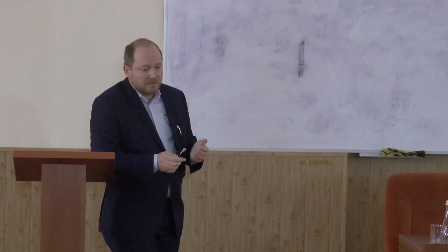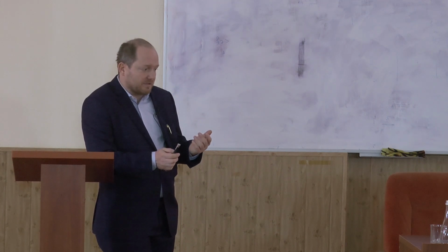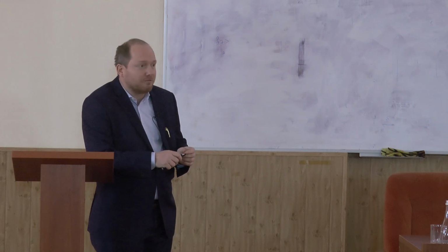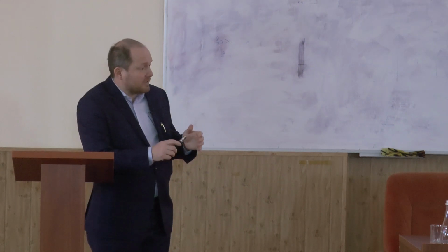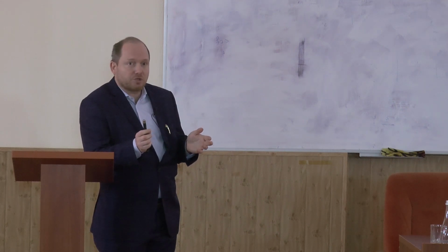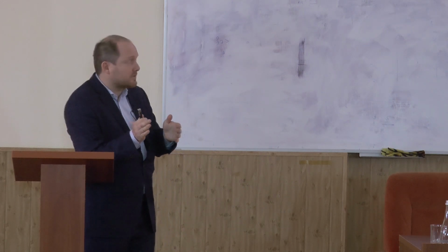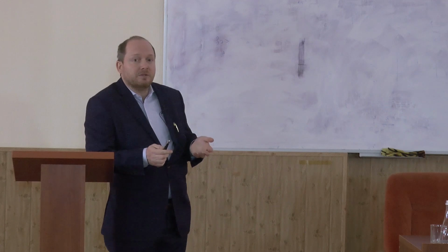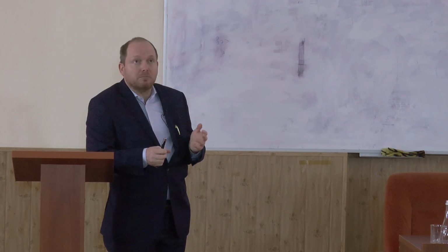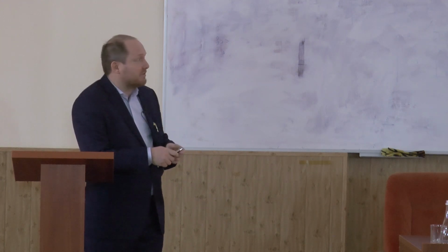Palladium is based on a custom processor, and with this hardware box, which is by the way a very expensive one, you can simulate the whole system. You have a Verilog description of the whole system, and then you can load this Verilog into the box, and then emulate the whole system. Protium is based on FPGA, so you can do basically the same with FPGA.